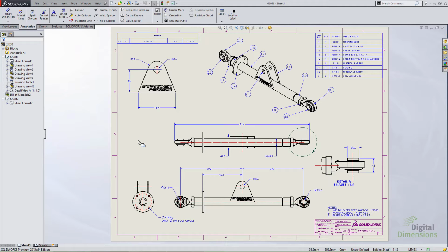And the answer has always been you create a text note and you type in the location, but the problem with that is pretty obvious. Once the drawing view moves, obviously that text note is no longer up to date. So it was always just a text string and a note. Now we actually have drawing zone functionality, which allows us to identify the location of views within a drawing.